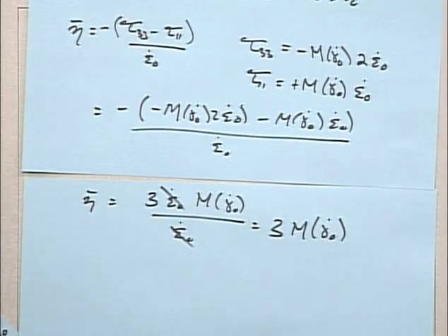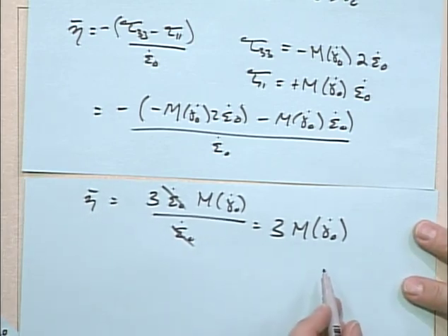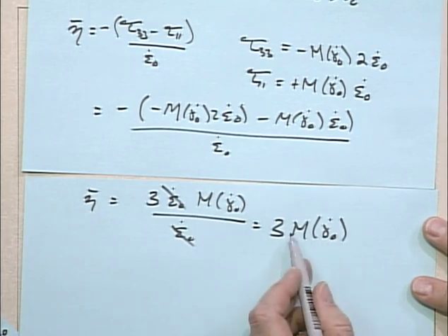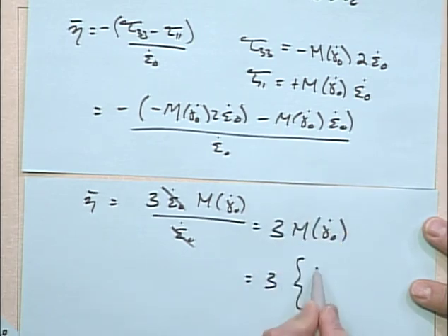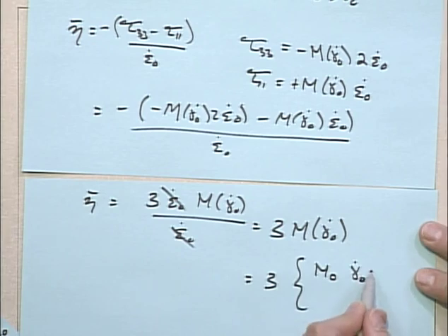The only problem is we actually have a problem if we try to sketch this or even understand what we've just predicted. This function says 3 times our m function, which is m naught when the shear rate, we're not even shearing, okay? When the shear rate is less than gamma dot critical, it's equal to little m gamma dot naught.